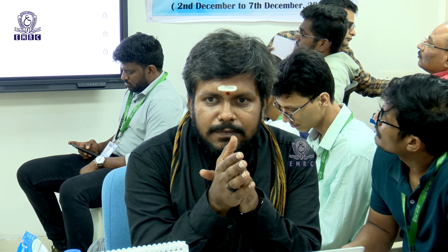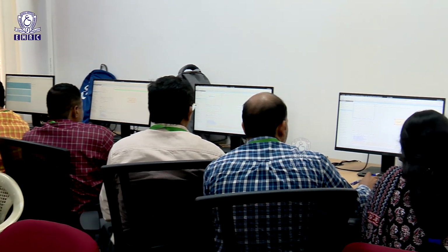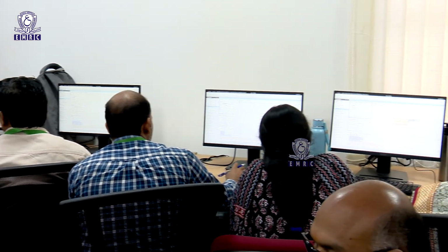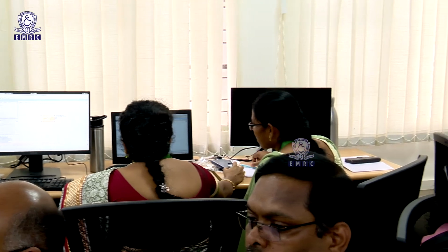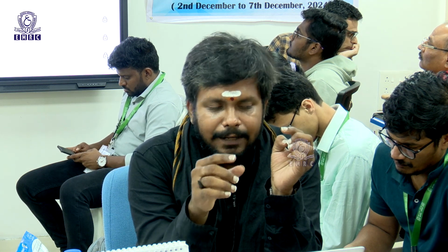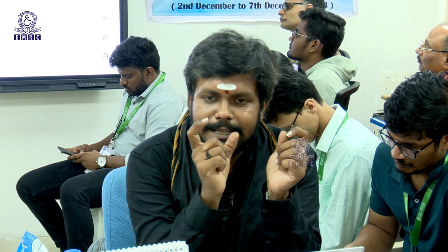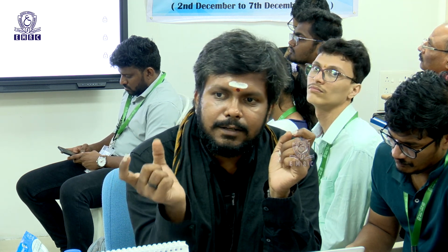But there is one specific port that is called ACP. It is the slave AXI ACP port. That particular ACP port is going to help you to accelerate your design. So the port specifically is called ACP, which stands for Accelerator Coherency Port. That is porting your design into an accelerator, and the SCU, the Snoop Control Unit that we were discussing, is going to help synchronize the design with your processor. That is like a synchronization circuit and your accelerated design on FPGA.